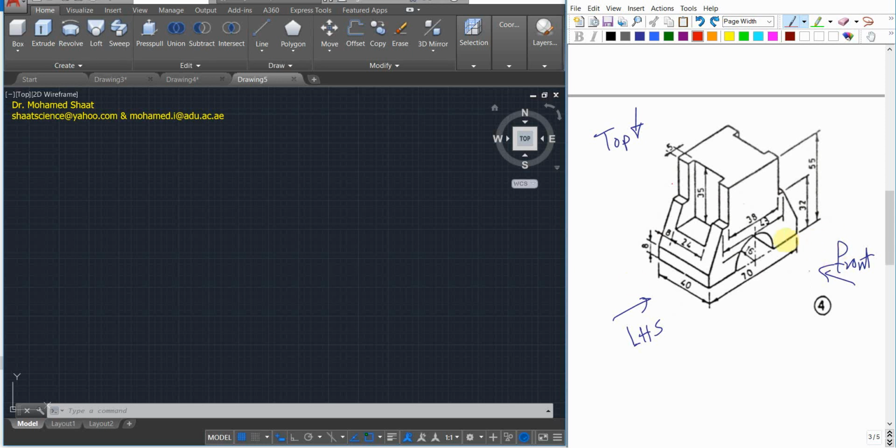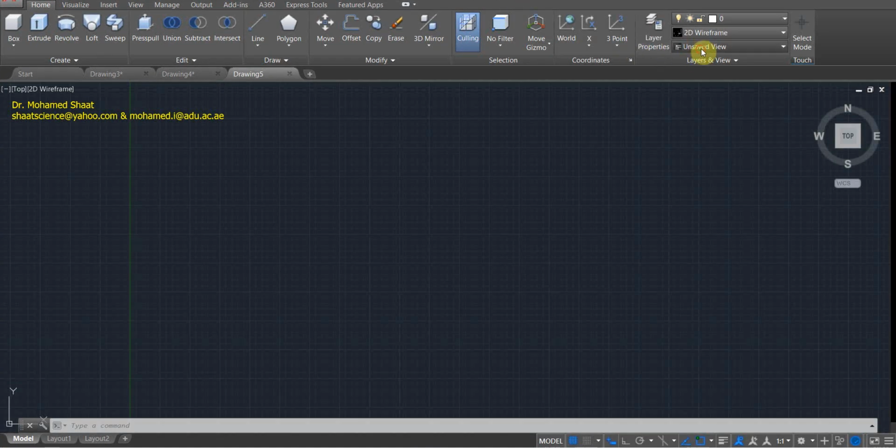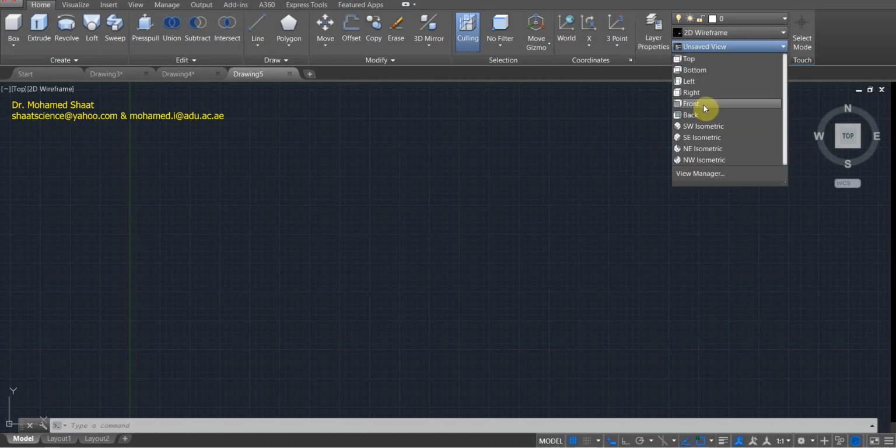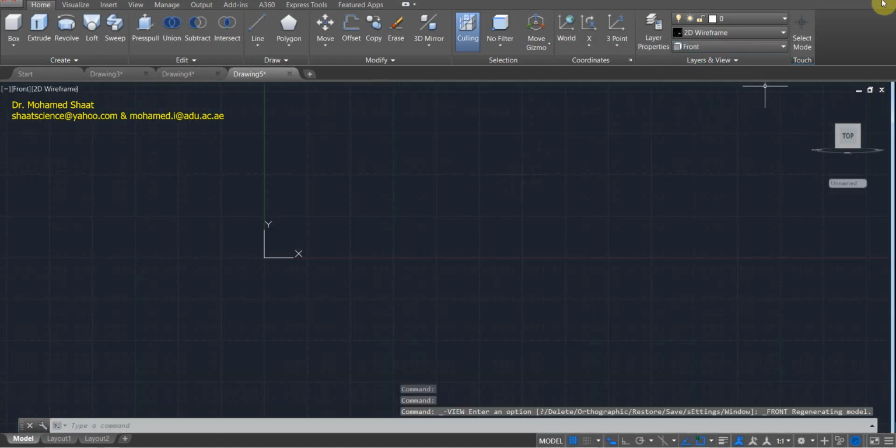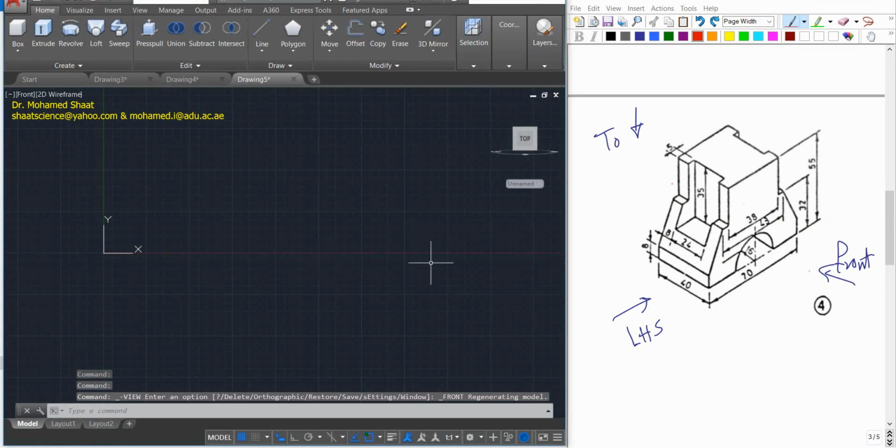Okay, so let us start with this shape and let us work with the same approach that I just mentioned, that we're gonna draw all of this entire shape here in this way. Then we're gonna extend it with the 40 millimeter. Then I'm gonna subtract this thing, right? So this is gonna give me 2 steps. So as usual, I have to switch to the front view. So I'm gonna go to the front, make sure that the used plane is the front view.